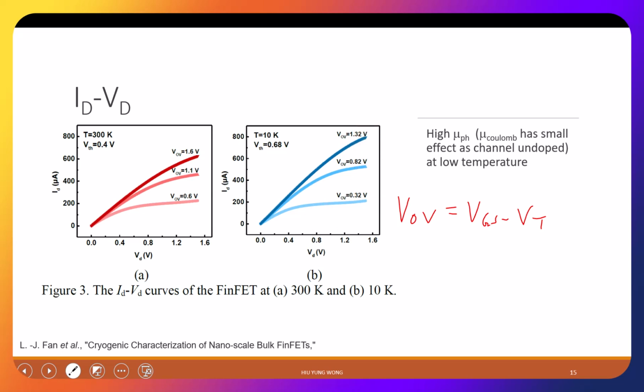Now, if they did not plot this and only plotted VG, you probably would see that they are similar. That is because now they take this increase in threshold voltage into account. I think that's why overdrive is helpful, because it's agnostic to how much the threshold shifts. So you're looking at how much above threshold the device is. That's right. But in a real application, you need the ability to reduce the VT to that level in order to gain that current.